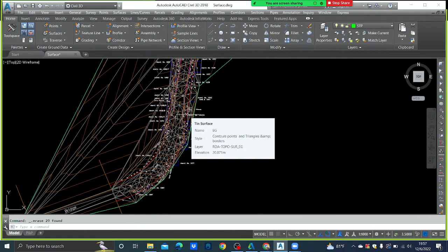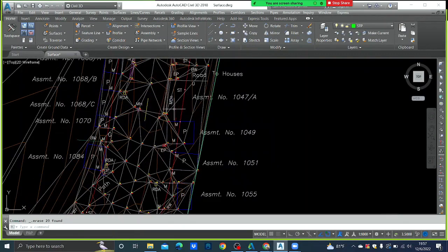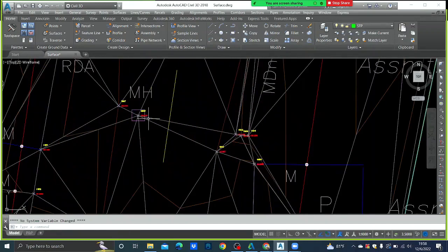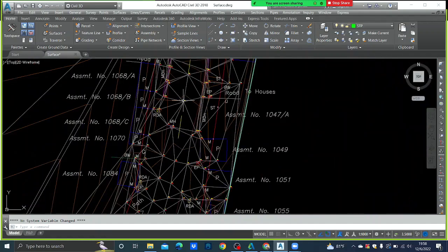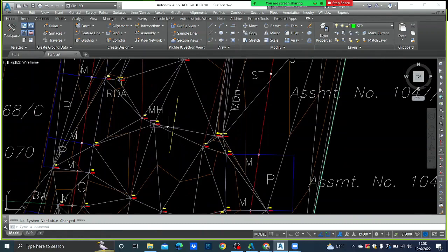So there is some concept called break lines. Okay, so we are going to make this tie edge and this tie edge and this CL into break lines. So once you make them break lines, there will be no lines like this cutting the center line or the tie edge. Okay, because they cannot cut. Cutting means it is not touching this point. Understood? Right, then we'll do that.